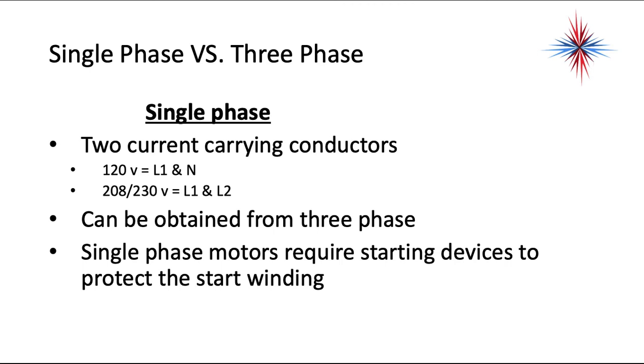Single-phase motors require a starting device to protect the start winding. Okay, so in single-phase motors, you're going to have a capacitor most often, and if it's a capacitor start induction run, you're going to have some sort of start component to take the start capacitor out of the circuit.